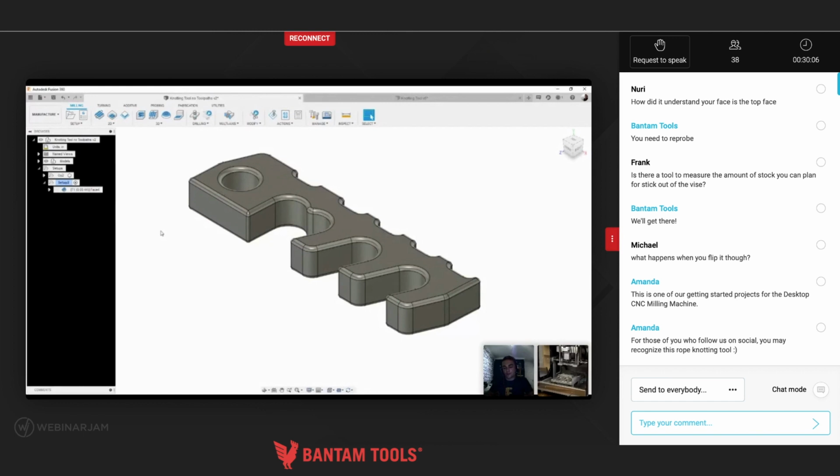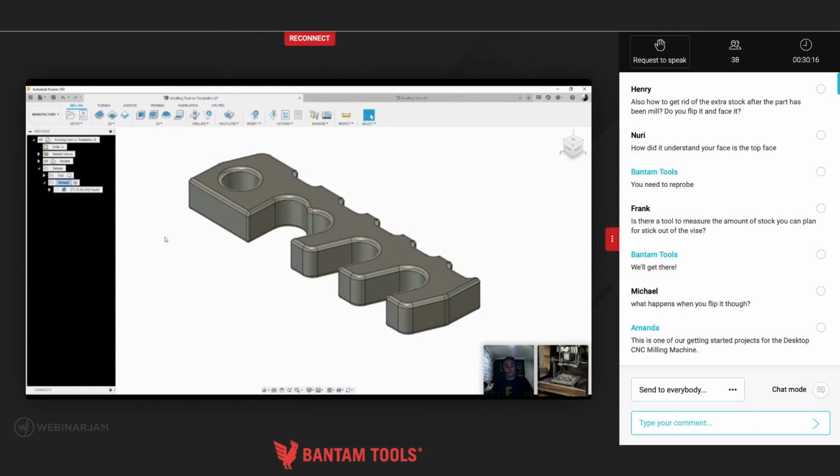Yeah, I think there's two things here. One, I think that comes with a little bit of experience. So again, the amount I showed you before, it's better to be safe than sorry as you're starting out. There's no golden rule for this, unfortunately. But the other thing is look at how you're holding your parts. Whatever contraption you're using, whether it's a fixture or a vise, look at the maximum depth that you can hold in there, because you can go overkill, but you can also go underkill, and it's better to be safe than sorry.